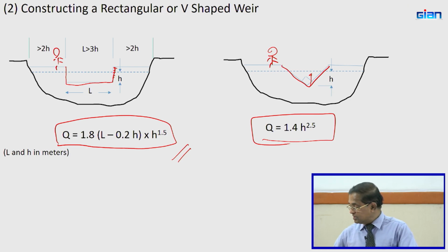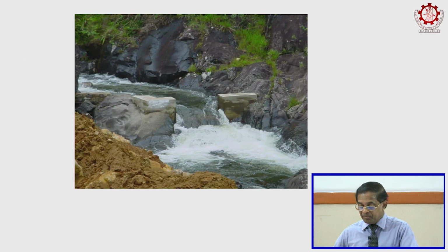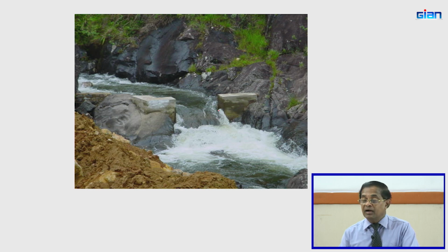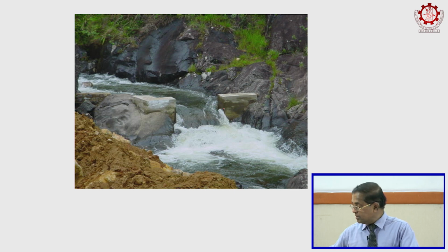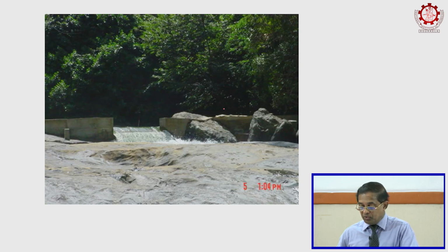So, in both projects we did in Sri Lanka under my supervision, we constructed this kind of measuring weirs. This is in one of the 2.5 megawatt projects. Before doing the project, we had 1 year's flow data. Therefore, we were assured that the data set given by the hydrologist is dependable. For the other project also, this is a narrow place, we could easily do it, but the other one was a bit wide. So, we had to do a bit of construction.